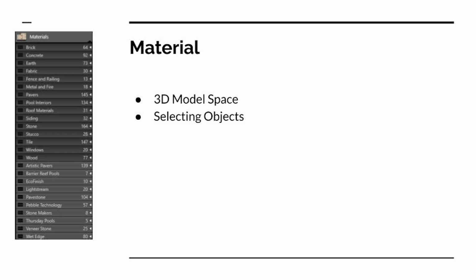Next, we move on to the materials stage. While we have created everything in the design stage on their respective layers, they are all generic. This is where we use the material stage, where we go through working in the 3D model space to select surfaces to change the desired material they are made out of. This is where you add your siding, roofing, change the texture of your ground, your patio, and so on. Material stage is quite helpful, and there is a large number of items you can use.